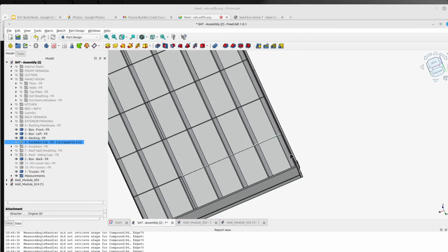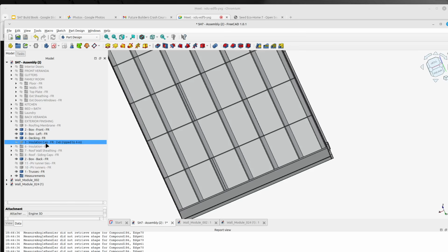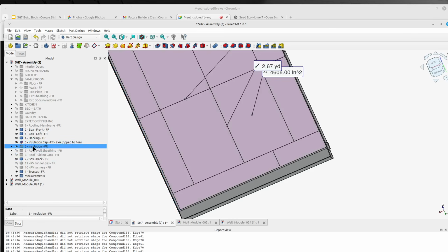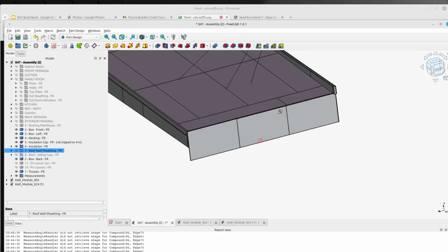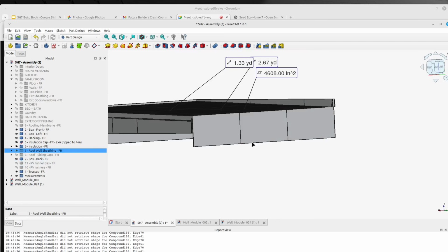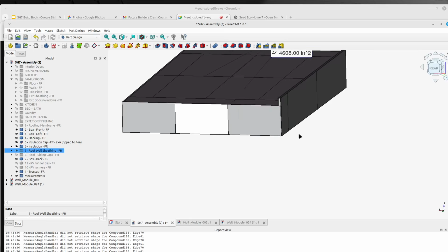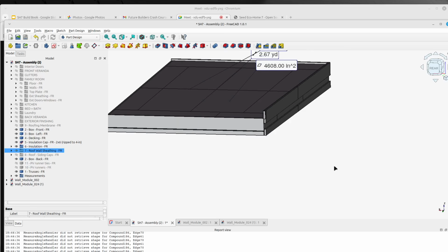This is a non-condensing roof. It has solid insulation on top of it. So that's foam board insulation. We're going to put 4 inches of foam, solid insulation. And then there's some more sheathing that goes right here over the front, side, and sides. That's just 1/2 inch OSB to cover that sheathing layer, which stabilizes the whole structure further.